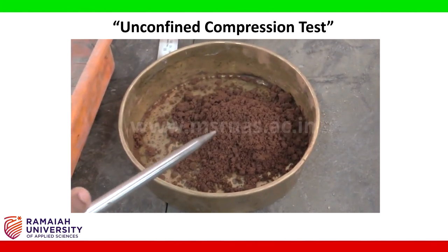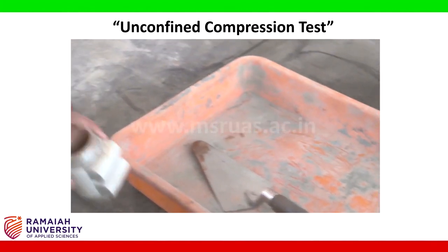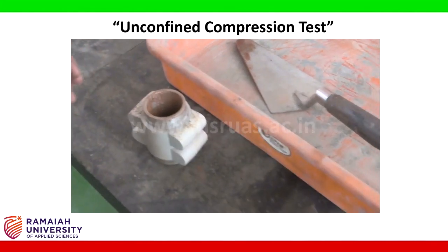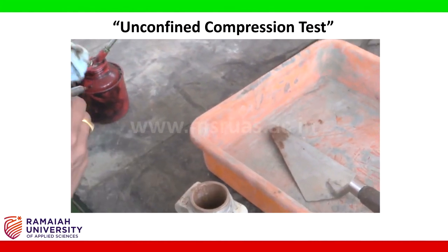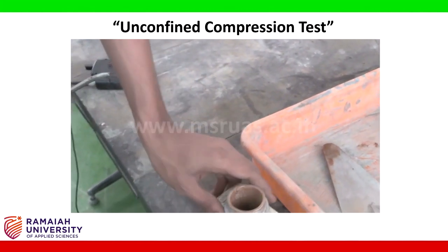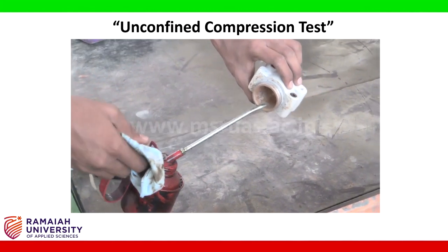After mixing the soil properly, now we can fill the soil sample into this mold. Before filling the soil sample into the mold, we should grease the inside surface of the mold using an oil so that the sample will not stick to the surface of the mold.